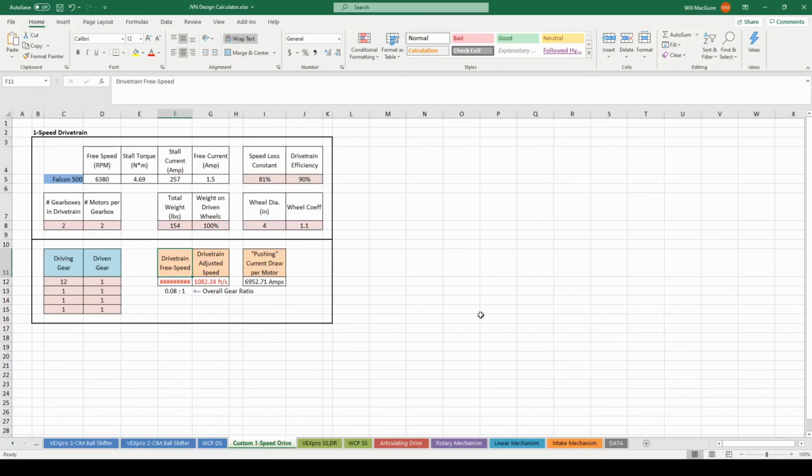The options for the driven gear teeth that we're going to be using are 12, which we've already used, 18, and 38. We've already used the 12, and the 12 can't be used on anything else. So these are our options. I guess we'll start off with trying to make the biggest reduction. Actually, let's just start off with making that 18, that 18, and that 38. Just trial and error, nothing too fancy.